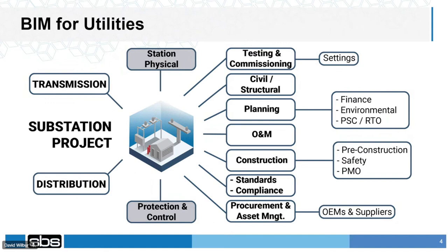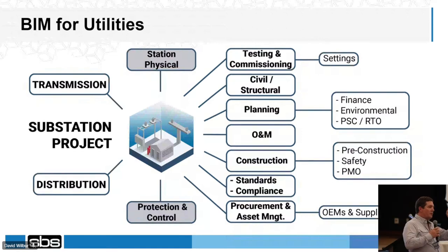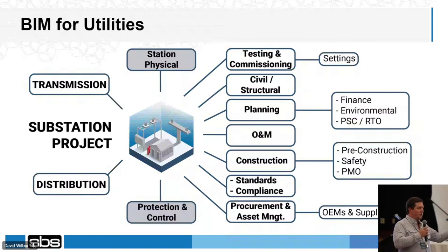The other thing to keep in mind about substation is we have two components. We have protection and control. We have physical. Those are at least two. There's probably others. Civil design. So being able to connect your physical design and your protection and control design on the same platform, rooted in AutoCAD, allowing us, as we were showing earlier, to seamlessly navigate from a physical design representation of a breaker or disconnect switch to the protection and control representation of that same device.